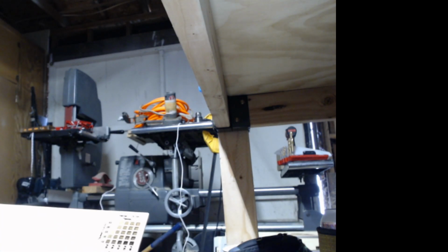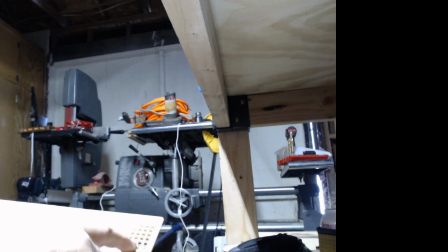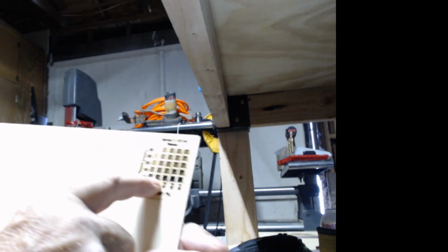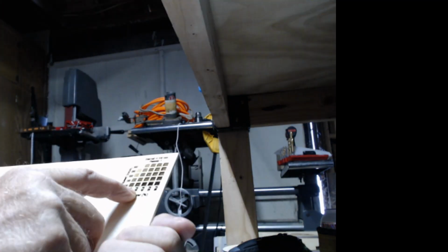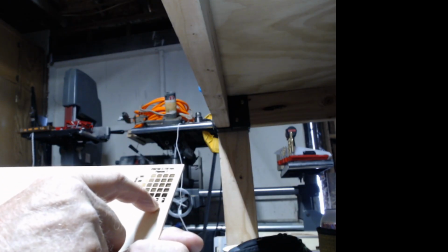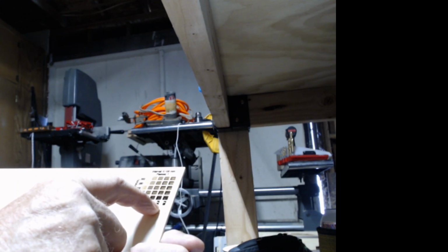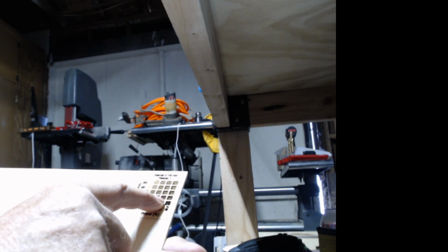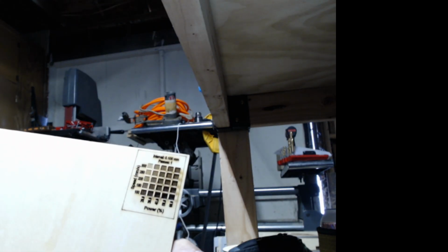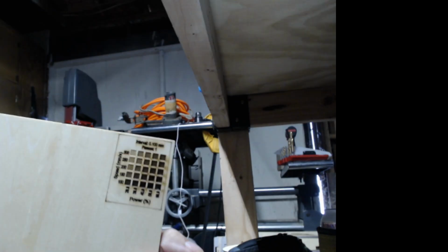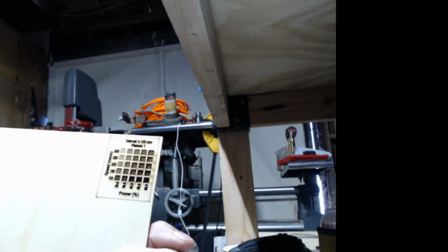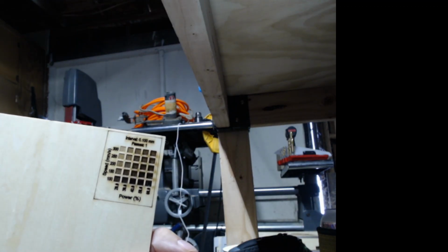And on the speed test, you look at the different levels and the different powers, and we can look at here. This is probably a good level right here, which is 30 at 100, or we could probably go at 50 and 150 as our power settings to get a good engrave out of it. So that's basically all you do. That's doing a speed and power test using Lightburn, and it's built in. You just got to go in and set up the settings you want to use.